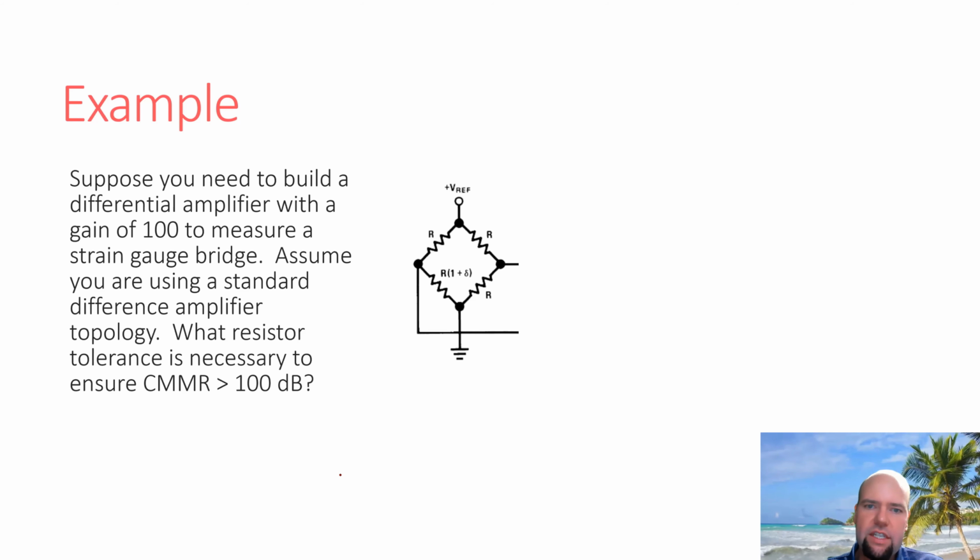And that can change the resistance of the material. So there's a lot of times where your physical sensing mechanism is in the form of a resistance. Also, things like photoresistors tend to do this too. But the idea is, if your signal comes in the form of a resistance, there's a lot of easy ways to measure resistance, right? You can just apply a voltage to a resistor and measure the current.